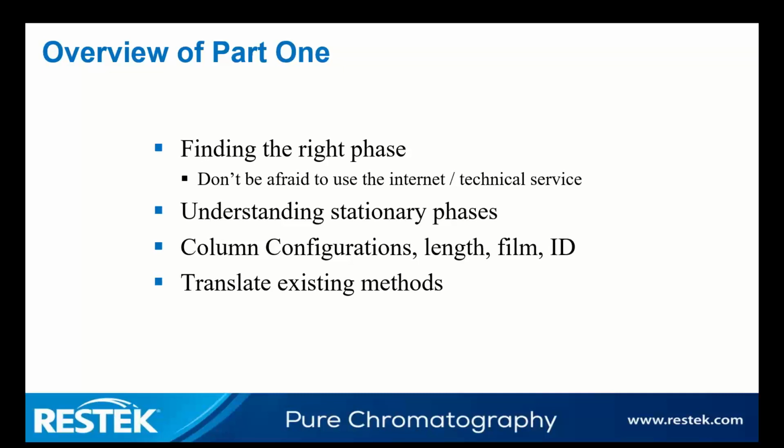If you're looking at drinking waters, you might be using a VMS type column or a Vocol or a variety of other columns. But the idea of the stationary phase is like dissolves like. So you want to find a stationary phase that's a good match for your target compounds. So for instance, if we're looking at aromatics or TPH, total petroleum hydrocarbon analysis, an appropriate phase would be the 502 type column because it has phenyl in it. And so that's an easy way to remember that.